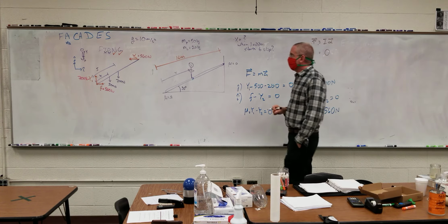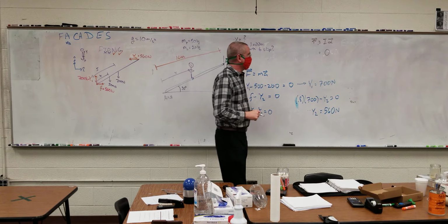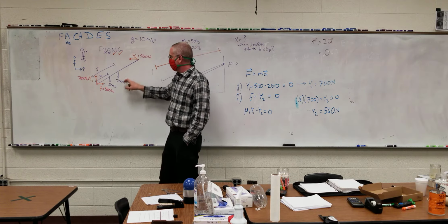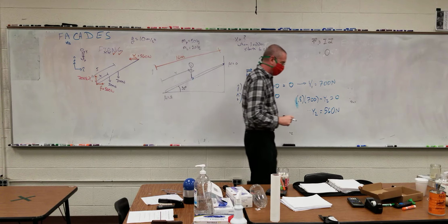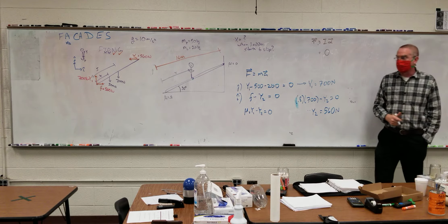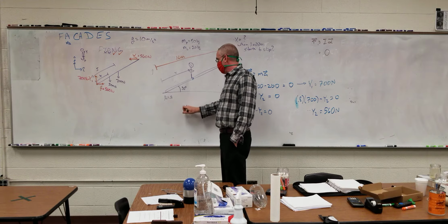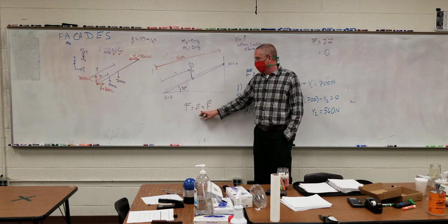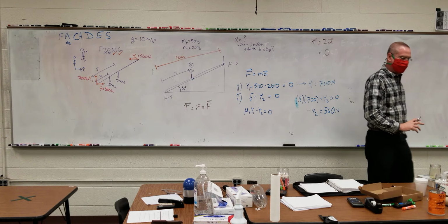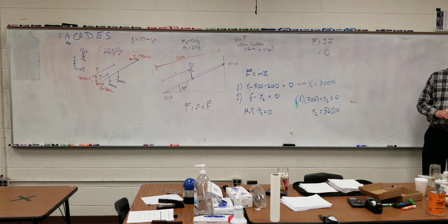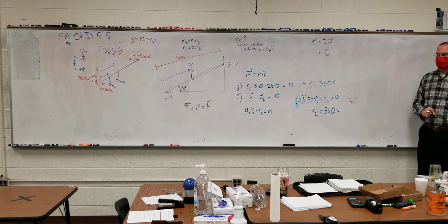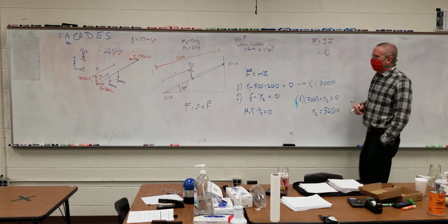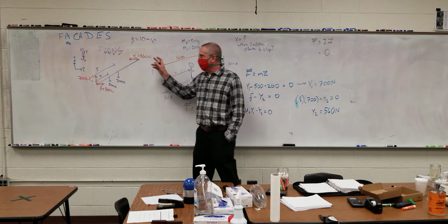Now torque. Torque is going to be the sum of all the individual torques. This is total torque, just like this is total force. So we need to figure out what is the torque being applied by these 1, 2, 3, 4, 5 forces here. But torque, if you flash back, is equal to R cross F. We have a moment arm and we have a force. Forces I got taken care of here. But the moment arm requires a pivot point, for something that's not pivoting. Thus, in the lab, I kept changing what the pivot point was. We can make the pivot point anything we want.